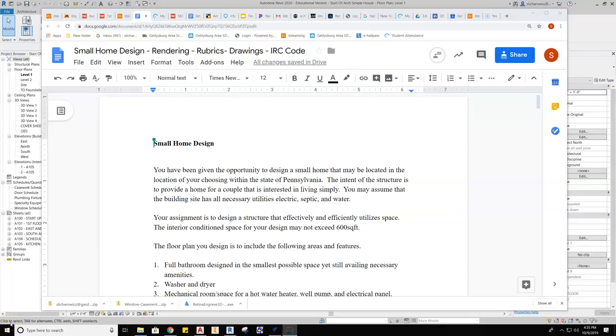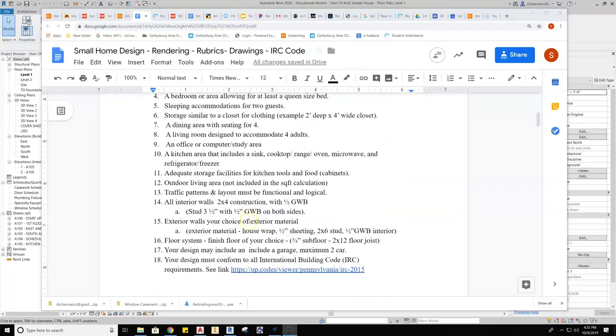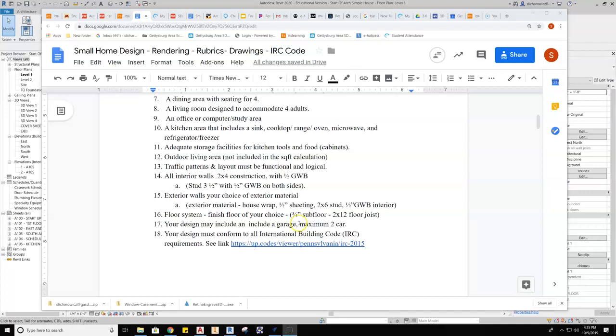Okay, in this video, we're going to talk about how to set up your levels for the small home design project where you're going to be creating a floor system and a wall system as specified under number 15 and 16. Your wall system is going to be your choice of exterior material, house wrap, half-inch sheeting, 2x6 stud, half-inch GWB interior, and then you have a floor system, 3/4 inch subfloor, 2x12 floor joist.